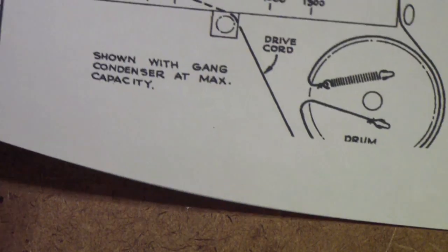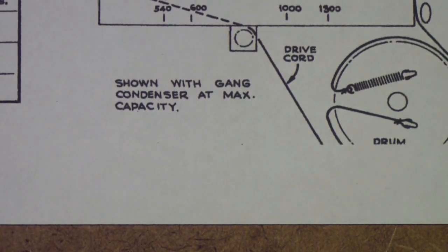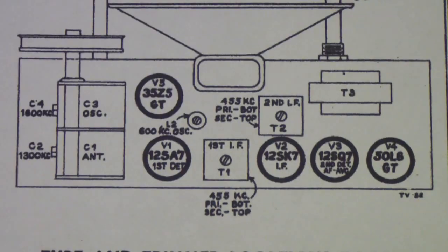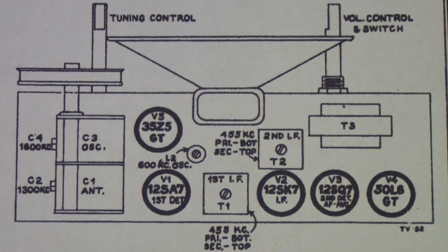I hope this has given you an idea of what it might take if you want to get into aligning receivers of this sort. In general, unless somebody has screwdrivered them, you generally do not have to align them to get them to work. Will they work a little better if you align them? Yes. But most radio stations are strong enough that in an AM radio, you really don't need a lot of alignment.